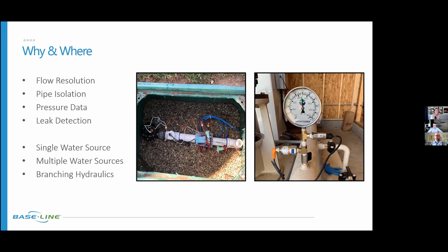So Andy, you've got a control point there with you. Hold it up and you can see that's in a 1-inch size, but essentially that's what's installed in that jumbo valve box. Yep. So again, we've got our flow sensor and then the pressure transducer, and then you can add a master valve of your choice, and all of the corresponding decoders are potted together in this pot right here, and then all you're left with is your one wire connection that will either go directly to the controller if it's conventional, or right on your 2-wire path.